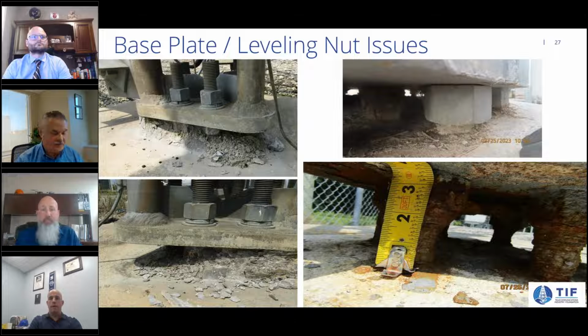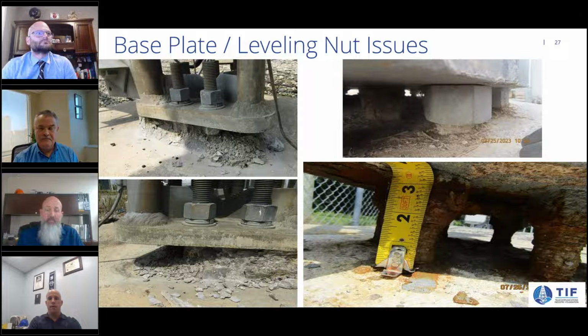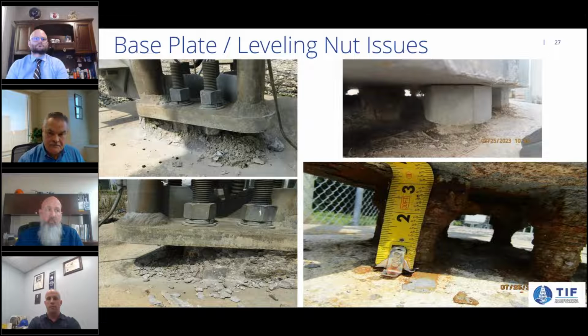Yeah. And then also for the grout stuff, not in all cases do we want to get rid of it. This is why during a maintenance condition assessment, an engineer sometimes has to be involved if the height from the base plate to the top of the foundation is too much, right? So this is again where we need multiple parties involved to make a coherent assessment and remediation. Great points, guys.